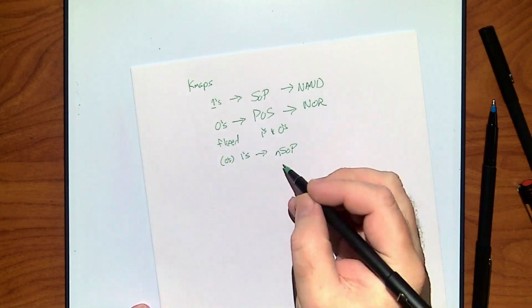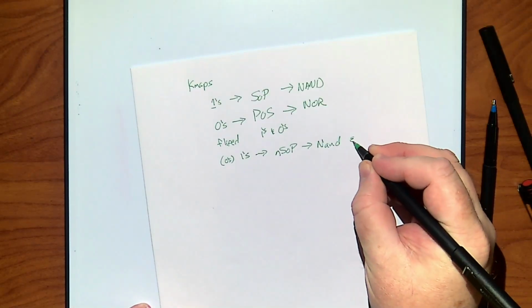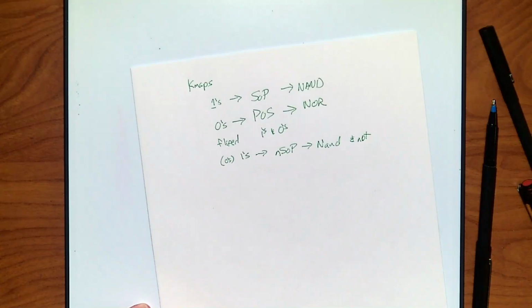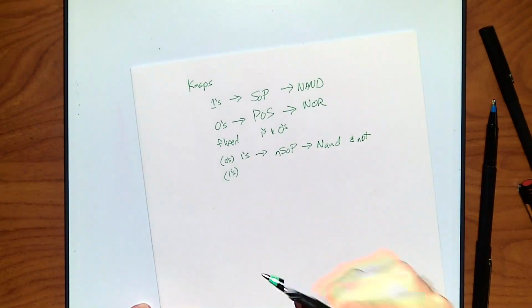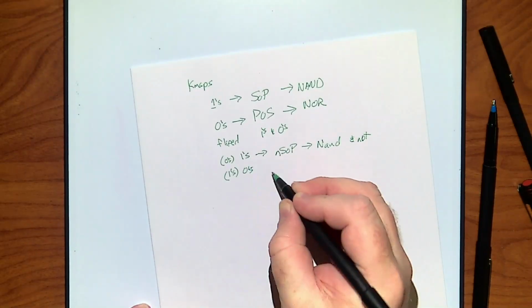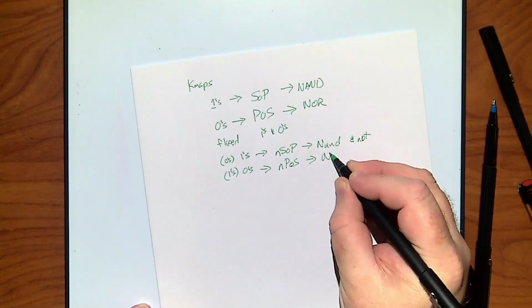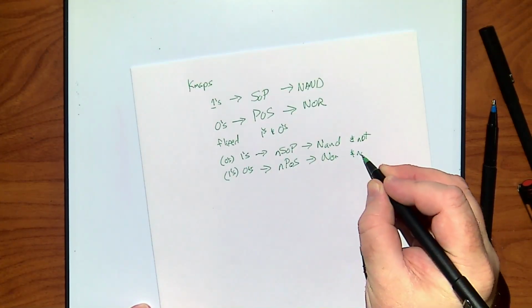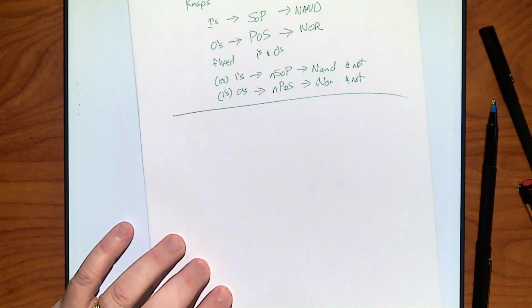So I could get the negated sum of products, which allows the ones to go by NANDs with a NOT gate at the end to flip it back. And the same thing, the ones, if everything else was a bunch of NORs, they're now zeros, which means I get a negated product of sums, which means I can stick with NOR gates and a NOT to undo my flipping. So you technically get four techniques that you can do, depending on what you want to encircle and what gate you want to use. All right. So this was one option.